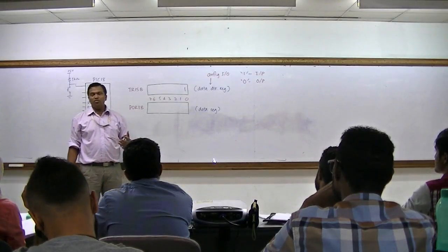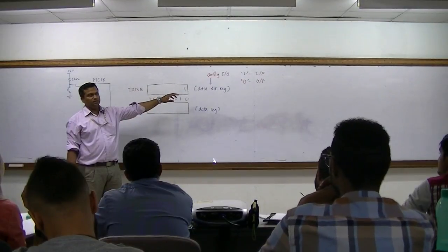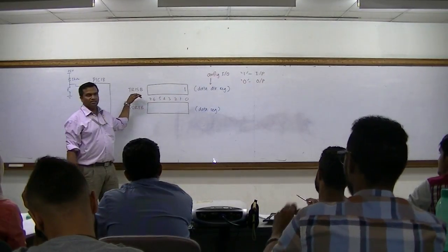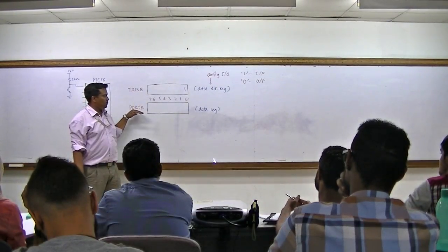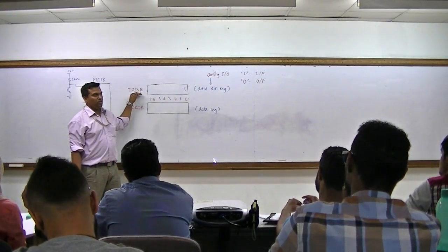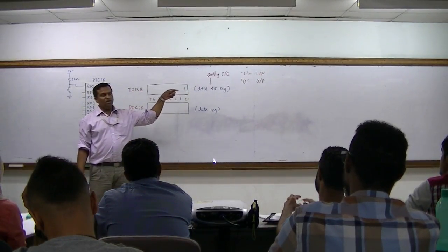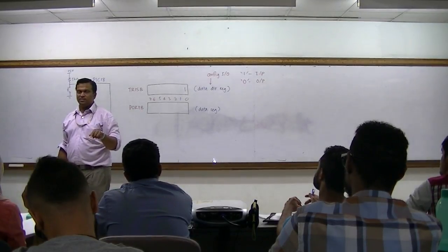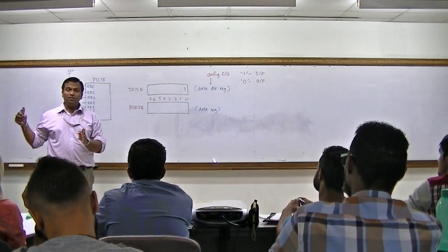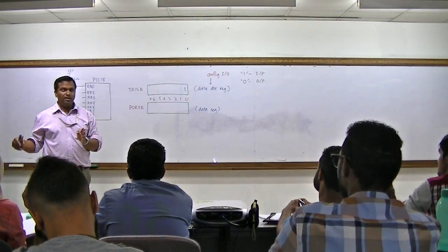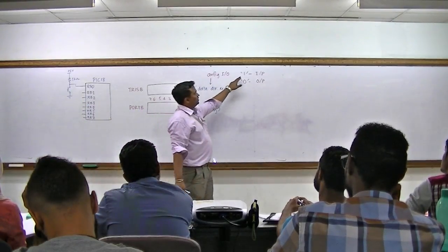The configuration of input and output is done at the data direction register, known as the DDR register. Each port has its own DDR register. Since we are dealing with port B, we need to configure at DDRB. Now the setting is, if you write the value 1 in the DDR register in that particular position, it means that that particular position in that data register will become either input or output. So this is quite easy to remember.